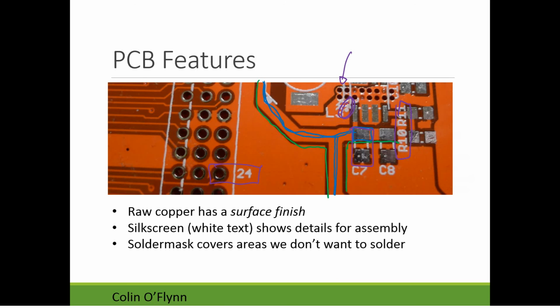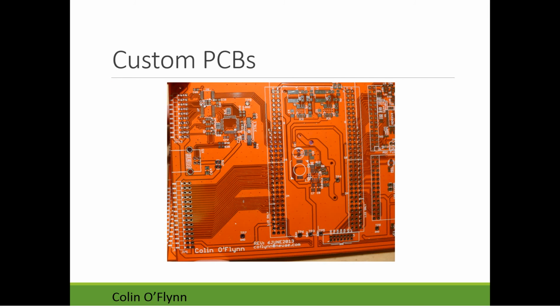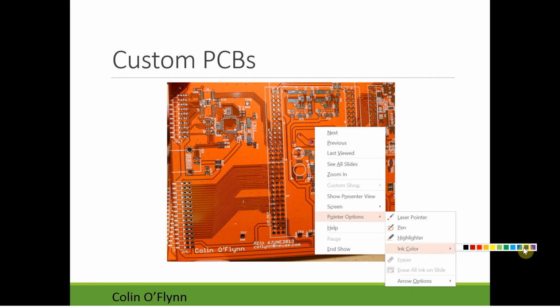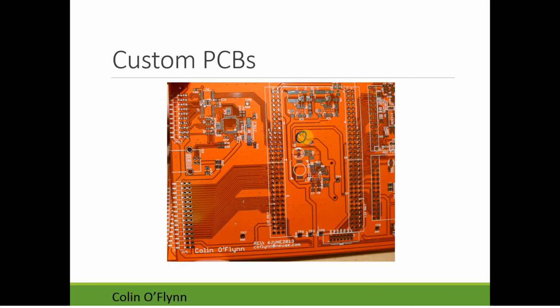Looking back at this example here, is there a good example of a via? All of these holes here are vias, and what they're doing is, if we were to flip the board over on the other side, this is a via here, and there's a whole bunch you'll see elsewhere on the board. Those are quite large ones. This is a via. There's some smaller ones here. And you can see that this trace here seems to end. It goes to this spot, and then there's nothing. That's because the via has brought the trace onto the other side of the circuit board, and you can continue writing it.